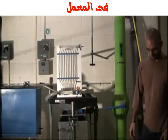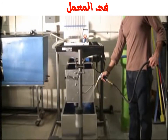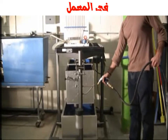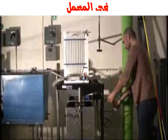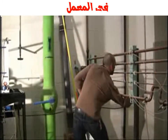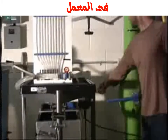The following procedures is for the startup of the apparatus. Make sure that the pump is turned off. If needed, add water in the bottom reservoir using a water hose such that 3/4 of the reservoir is filled with water. Ensure that the power cord is plugged into the wall. Make sure the valve of the apparatus is turned off by turning the red valve clockwise.